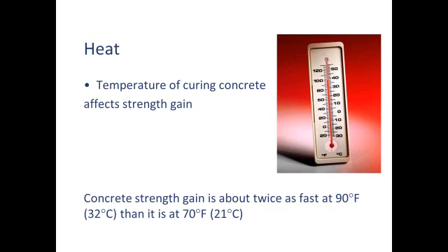So a good rule of thumb is that the whole hydration process is going to react about twice as fast at 90 degrees Fahrenheit than it is at 70 degrees Fahrenheit. And there's the metric equivalent for you. So when it's hotter, things happen faster. It's like the clock speeds up. You're getting free time.